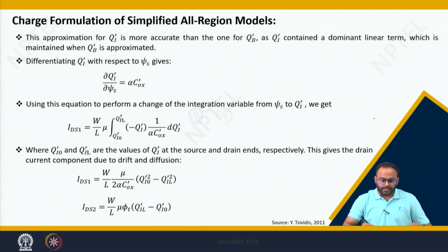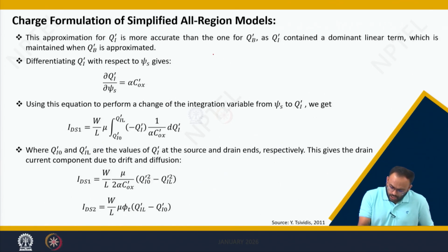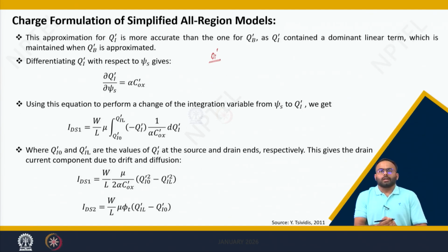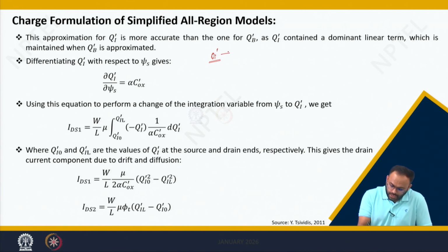In this lecture, we will see whether we can formulate our drain current in terms of charge instead of using the surface potential. If I am going to formulate the current equation in terms of charge, then I need to linearize this charge equation, because I know that the surface potential and the inversion charge are strongly non-linear.